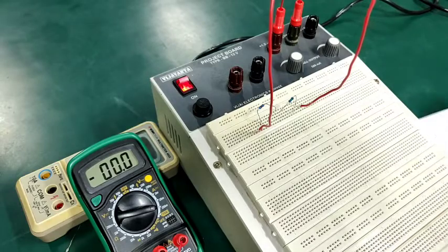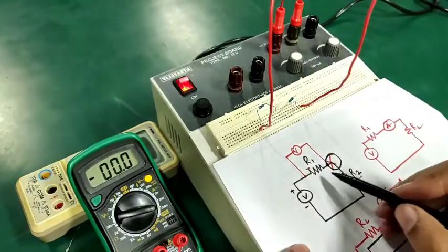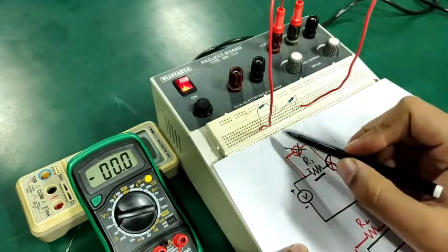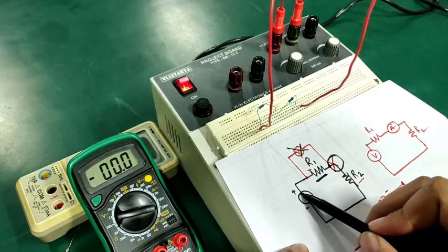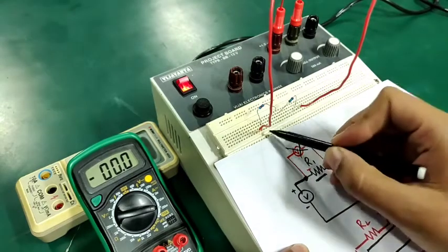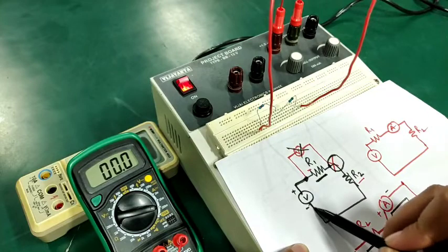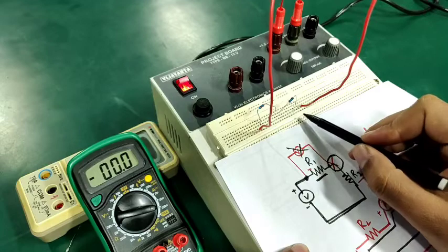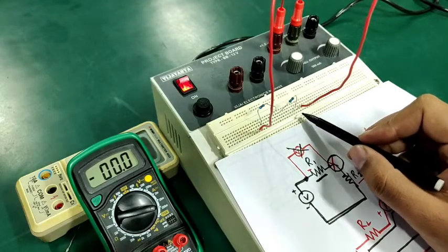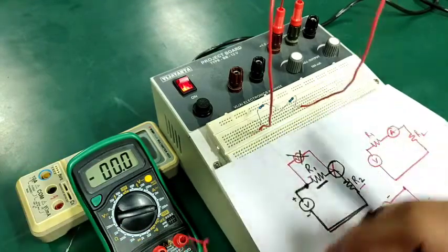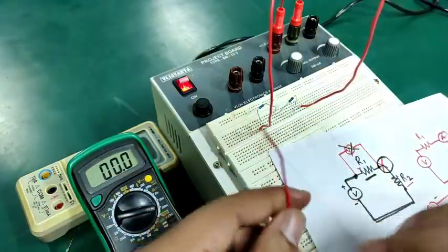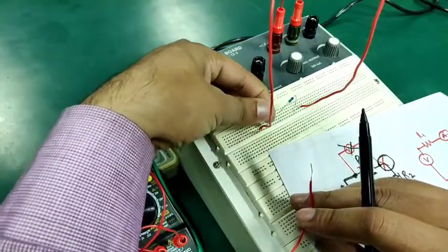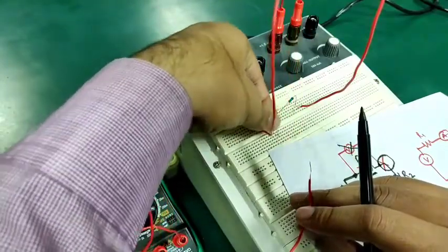Okay, so this is my normal series circuit, in which there is a resistance R1 and a resistance R2 in series, and the positive end of the voltage supply is going to the first terminal of R1, I can see here clearly, and the negative supply is going to the other terminal of resistance R2, which is here. Okay, so now this is the positive terminal of my ammeter. So what I am going to do is take out one terminal of resistance R1 and put it somewhere else.